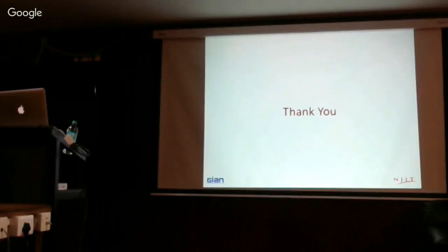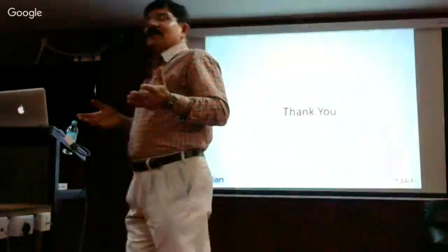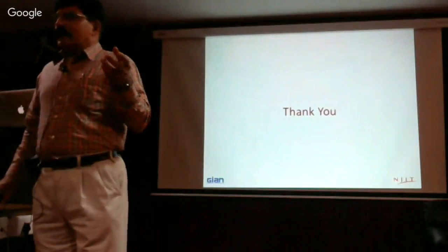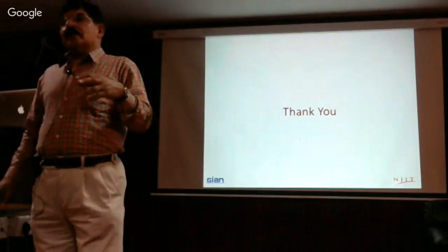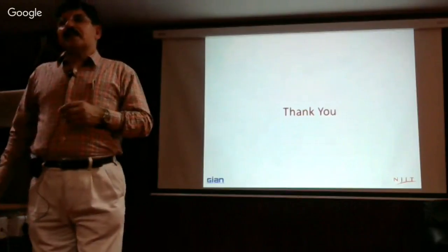When you do the device, you select a particular technology. What technology was it? Silicon, with MOS 11 and BSIM models. But what technology is that? 0.18 micron technology? 180. What is the threshold voltage in that one? You don't know. Why don't you know? Where is it hiding? Those models are hiding something. So sometimes we do not understand what parameters they have used.